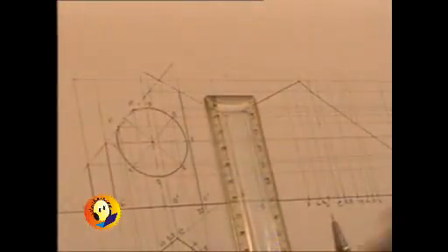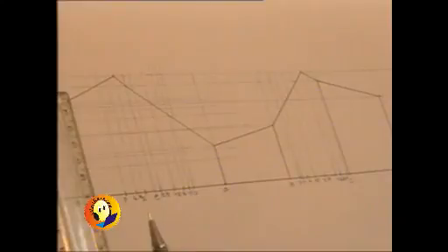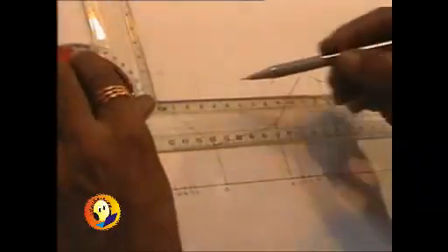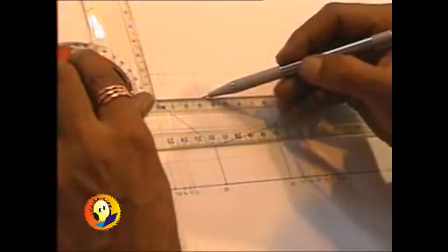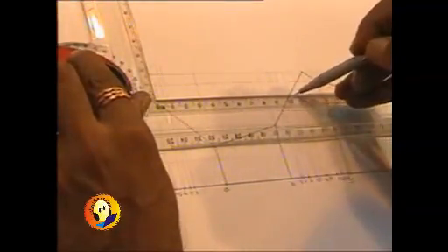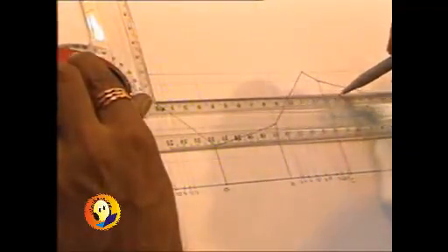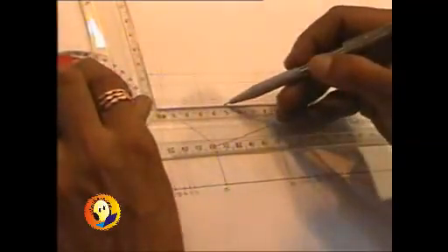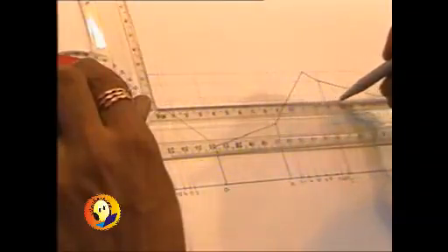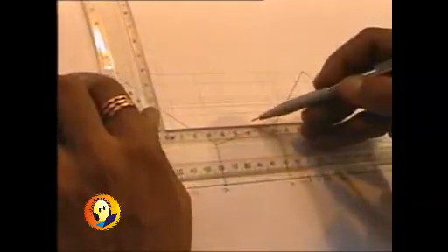So all these paths should be drawn, and of course they should be extended even beyond, because we have got the same generators on the other side also for face BC. So these are all to be extended. And we are required to find out the respective intersections also.